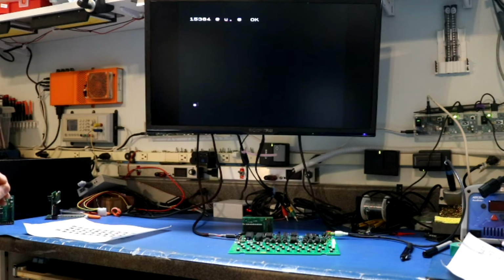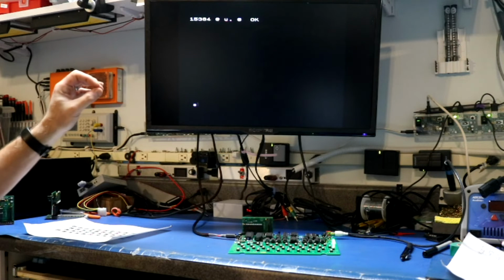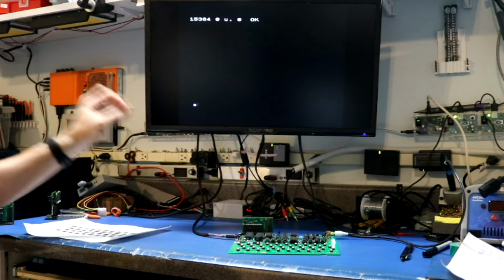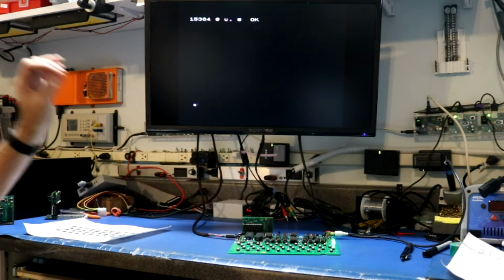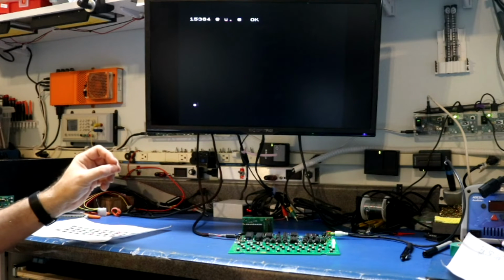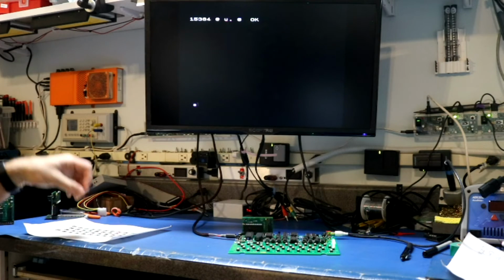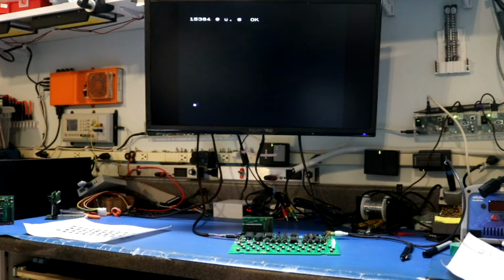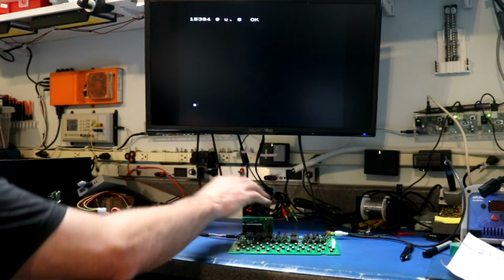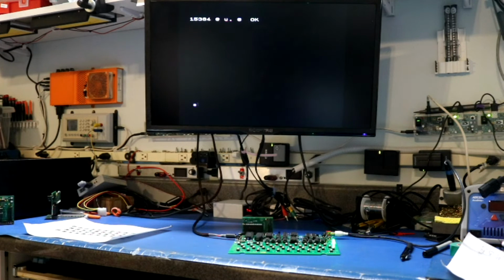And the reason it says 0 is because the top of memory is now at 65536 instead of 16384, and I believe it just truncated that to a 16-bit integer. So it rolled over, 65536 is actually 0 if you hack off the upper bits. There we are, our memory expansion is working as it should.